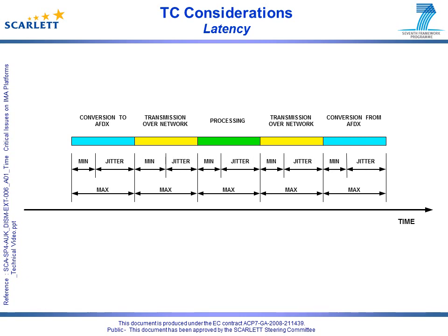Jitter is the variation in the timing due to the tolerances in the system components, a large part of which is a result of the asynchronous nature of the AFDX elements. The jitter from each action must be combined to determine the worst case. One final consideration is the sample interval. It's important to emphasize that the time window starts at the moment the event occurs, not the moment at which it is detected. Therefore, sampling interval may play a significant role in the overall timing budget.